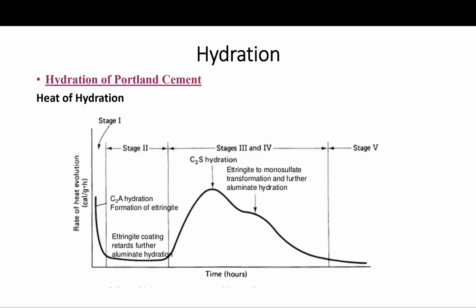Okay, I'm going too fast here. I'll go back. So you remember, let's talk about the heat of hydration. You remember this graph, which is the heat of hydration curve for Portland cement I showed during the talk about the heat of hydration calorimetry. And the heat of hydration, we discussed during the talk about the hydration of C3S and C3A. This curve is the heat of hydration curve for Portland cement. And notice how it looks analogous to the C3S curve.